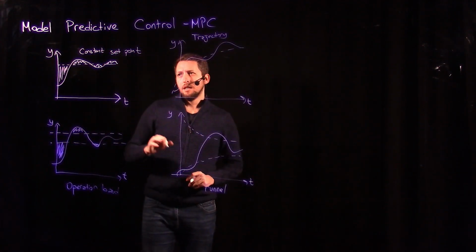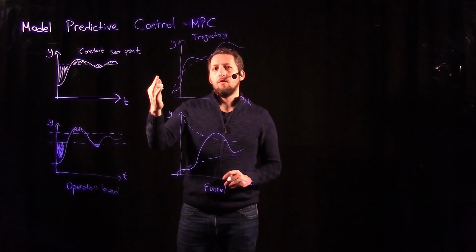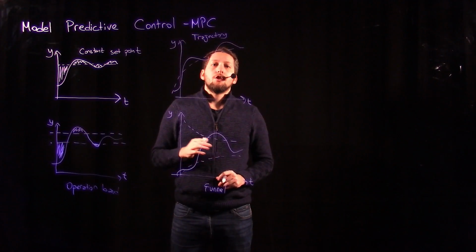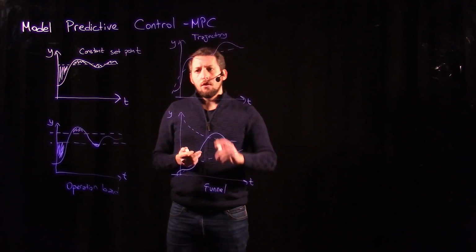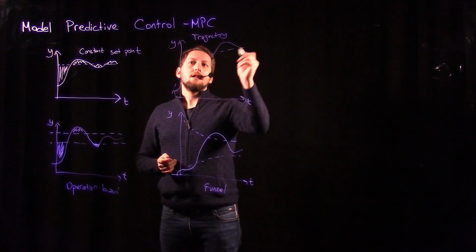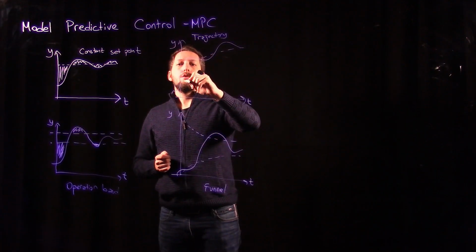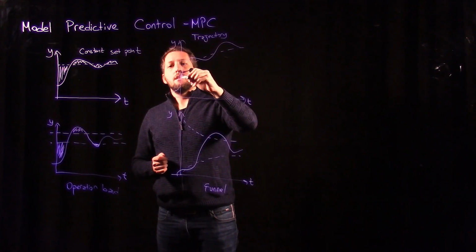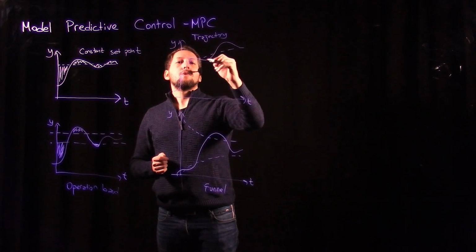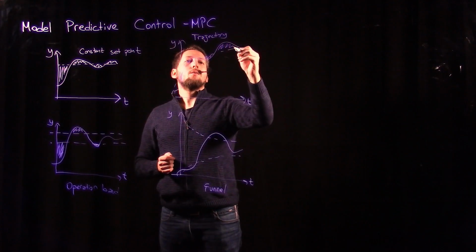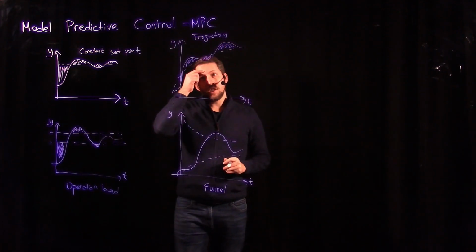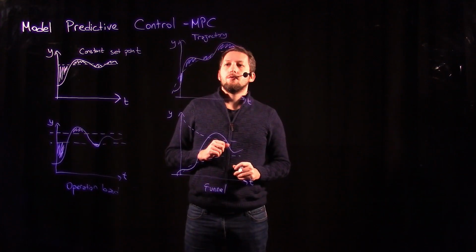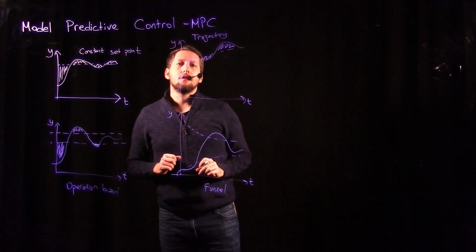Another thing: maybe you have a unique profile of input or reference, and this could also be named a trajectory that you want your system to follow, which is represented by a dashed line here. When you have such an actual response, then this part should be taken into consideration and, let's say, included in your cost function. So this becomes the error signal for you.